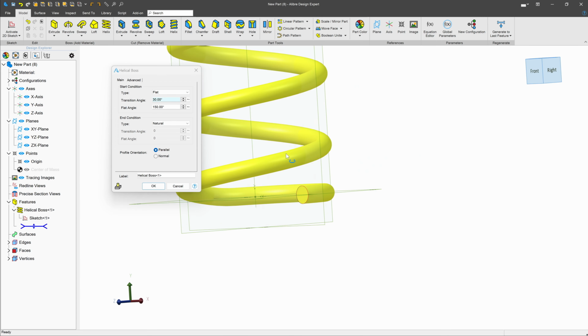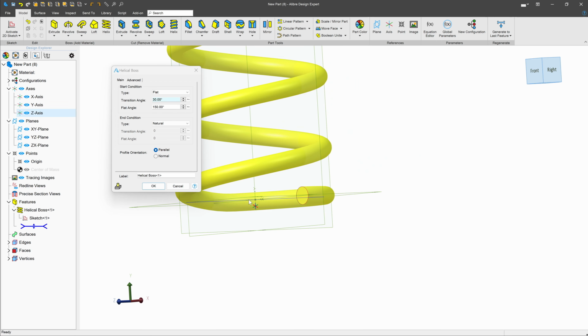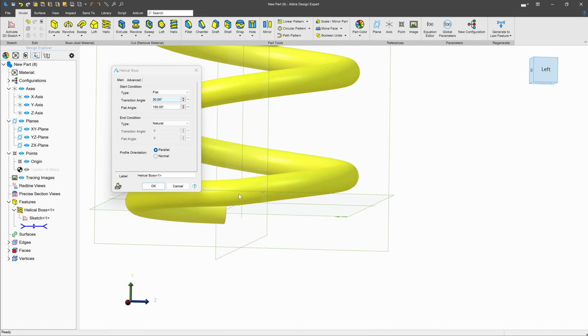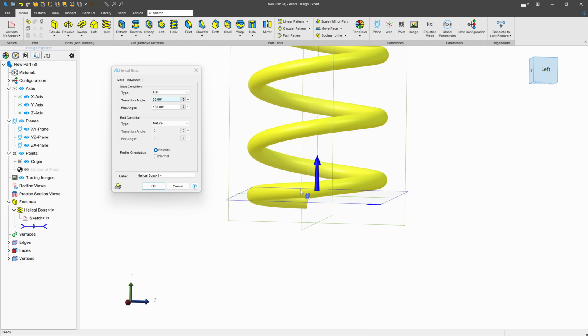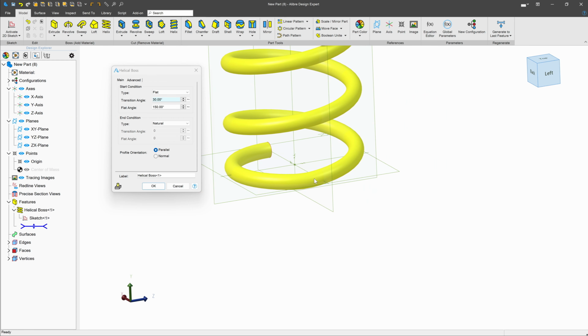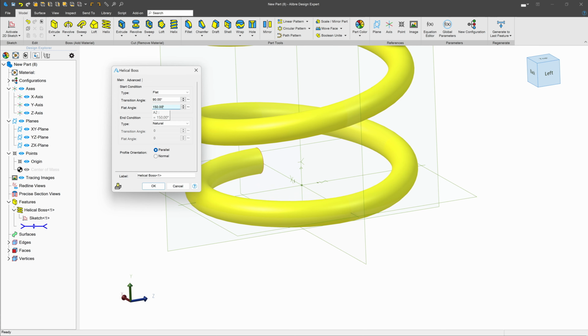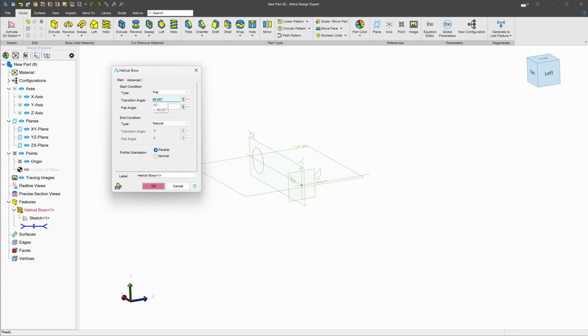And just like that, we're going to be flat for 150 degrees going around, and then we're going to spend 30 degrees transitioning, which you can tell that looks like a pretty sharp bend. But as you can tell, we are transitioning for 30 degrees into our regular pitch. So maybe I'll move this transition angle up to 90 degrees. Maybe I can make this, I'm going to try for 270 and see how that goes. Nope.